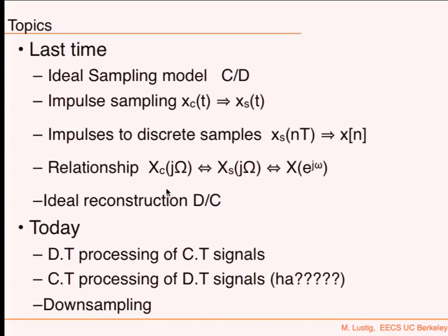So even though you are sampling and you are doing anti-aliasing filtering, you have to understand that the outer edges of the frequency of your discrete time signals are contaminated with signals that you didn't mean to be there. So you always have to understand that. One of the ways to deal with it is actually to oversample, so then you can basically crop these away.